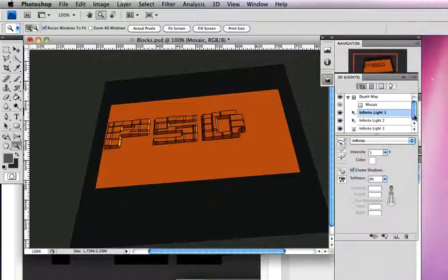All of the lights are exactly as we set earlier. No shadows from 3 or 2, 3 set to point, color set to white, and 2 set to that grey, and again no shadows are being created. Okay, so now we're going to have a look at where these lights are actually coming from. To do that, we're going to come down here to this little button. It's an eye with a light bulb, and that's going to show us where these lights are.